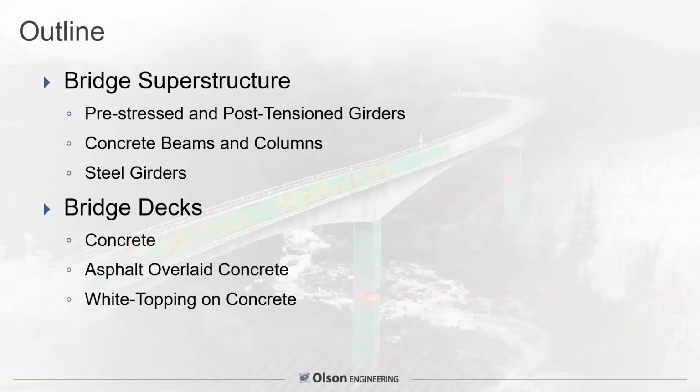anchor bolts for integrity. In terms of bridge decks, we'll be talking about the applications of NDE to bare concrete decks or thin epoxy coated decks that are still basically concrete. We'll also be talking about asphalt overlaid concrete, a more challenging problem to assess the condition of the deck, and white topping, that is concrete put on as a repair and bonded to concrete deck underneath.